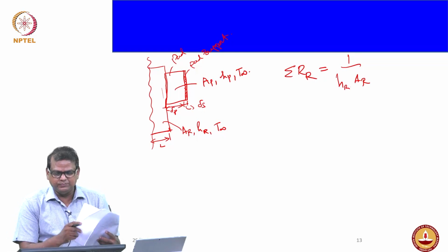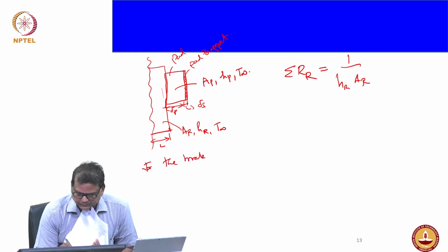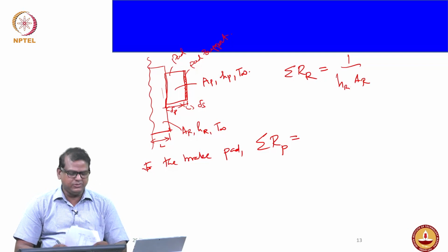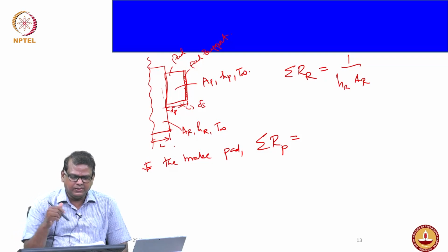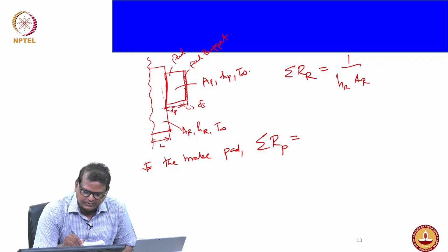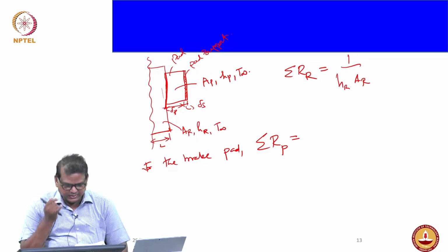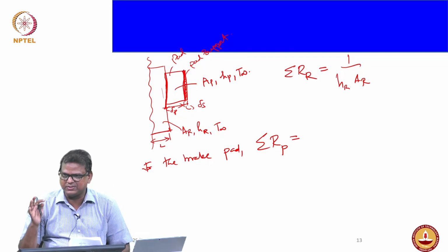Now, we will talk about the thermal resistance at steady state for the brake pad. Tell me, what do you expect for the pad here? What heat transfer, what heat resistance do you expect here? Look at the diagram. Okay. So, you have one conductive, that is clearly given, and you have a convective also, right. There is also one more conductive between the pad as well as the pad support. Three resistances are involved there.